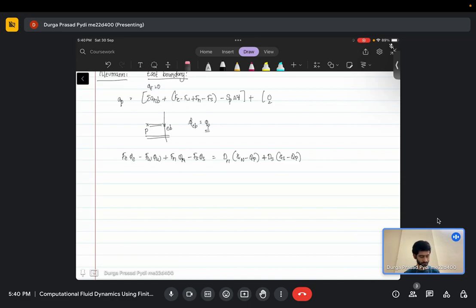So in this equation, what this Fv will essentially be equals phi, or in our case phi is replaced with U if we are writing the x momentum equation. So this will be Up minus, if we are using central difference, Uw plus Up by 2, and everything else remains the same: Un plus Up by 2, and then Us plus Up by 2.